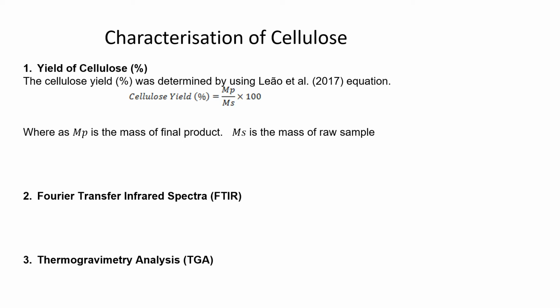The equipment was operated with a resolution of 4 cm^-1 and a scanning range from 4,000 to 400. The third characterization is the thermal behavior, and we used thermogravimetric analysis, carried out at a heating rate of 10 degrees C per minute from room temperature to 800 degrees C.